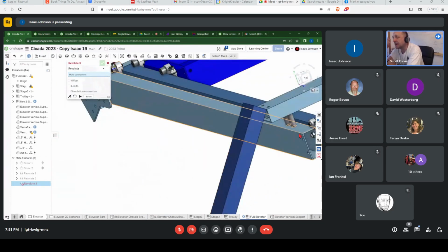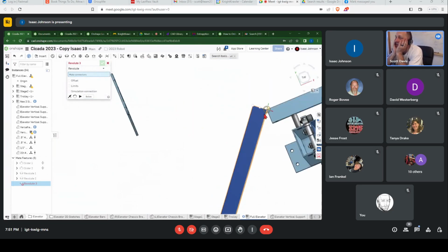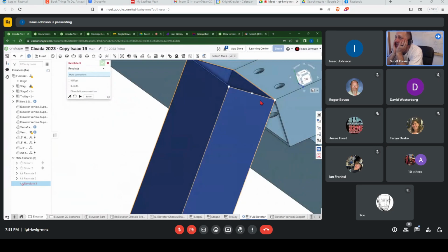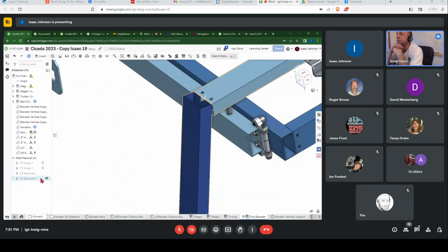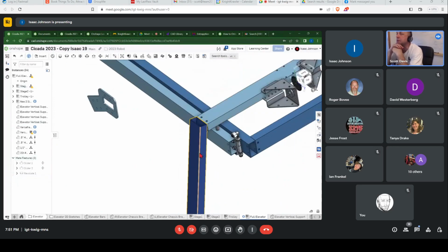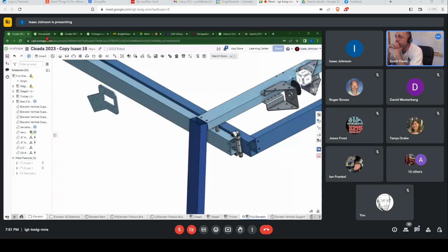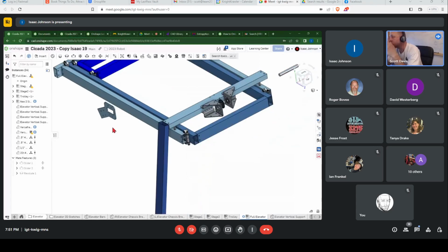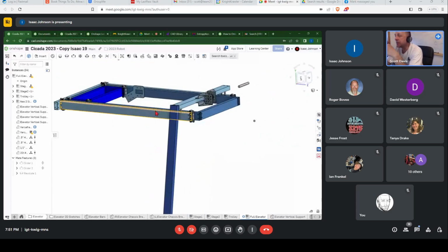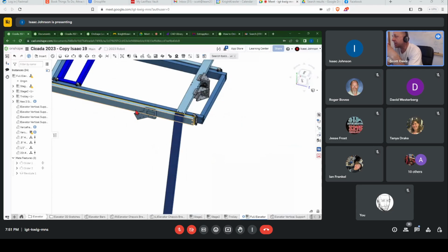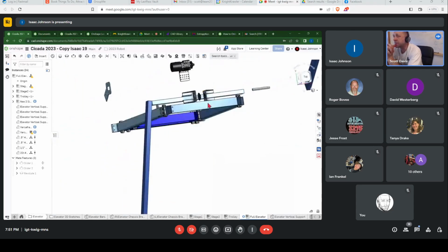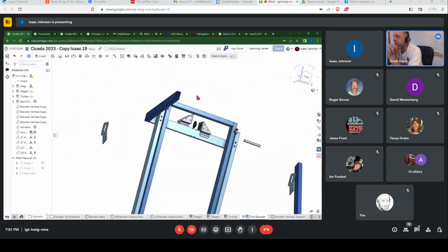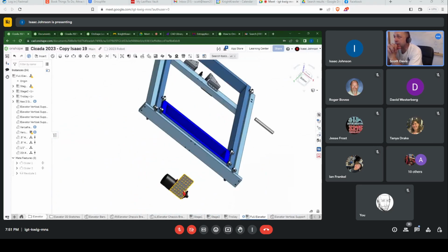Onshape's kind of smart about that, saying, well, obviously what you're trying to do here is a hinge. So Onshape's pretty smart. If it's not doing what you think it should do, it's probably because you've given it bad instructions. And sometimes you just have to play with it, and then you'll figure out, oh, I get it. Now I see what it's trying to do. A good question. The different mates, I think that separates beginners from intermediate people, is once they start understanding the mates and how to fasten things together, especially when you're talking about allowing movement.